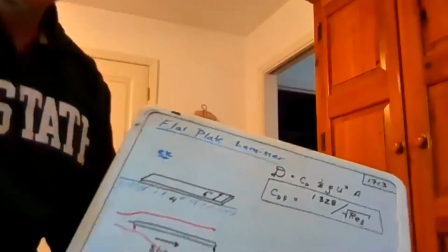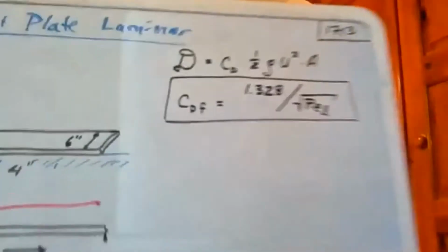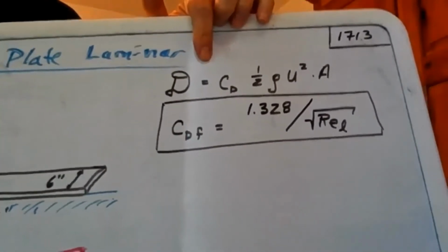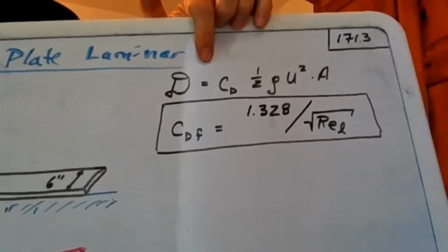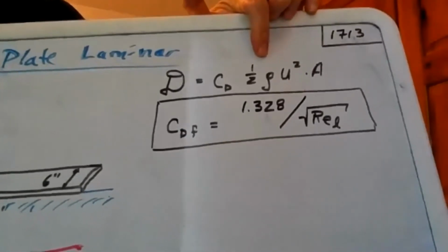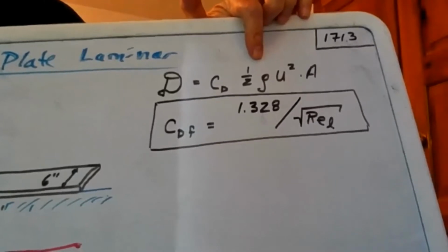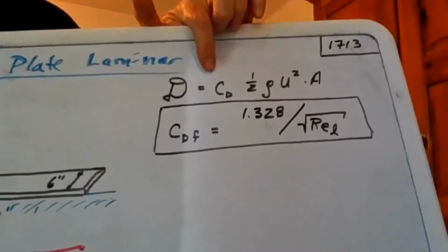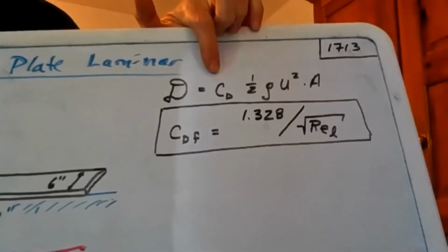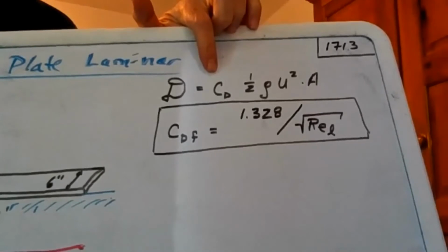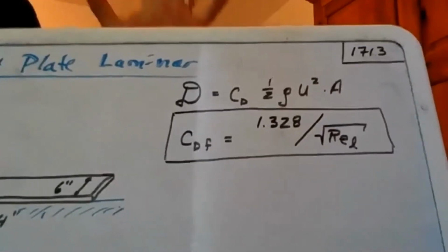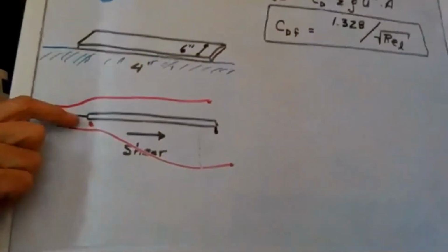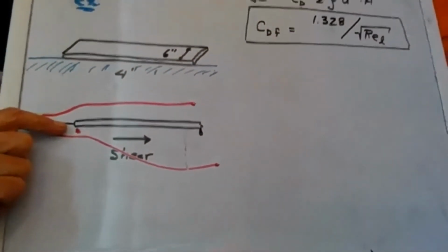So the alternative is to go back to the basic equation for drag. And once again, it's helpful to think, okay, there's some sort of fluid dynamic pressure, 1/2 rho u squared, and we're going to multiply it by area, but then we're going to adjust for the particular situation. And if this coefficient of drag is 1, hey, what we basically have is a blunt object facing flow. All right, well, we don't have this in this case. We don't have an object that's blunt and facing flow.